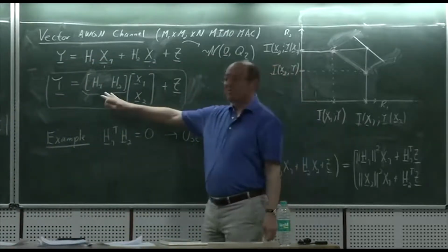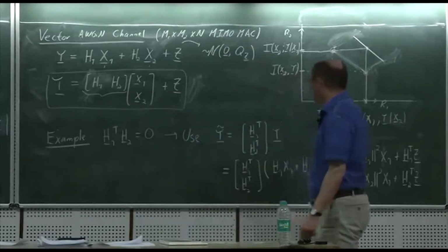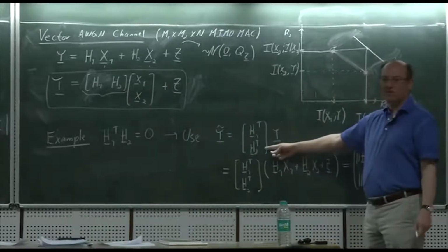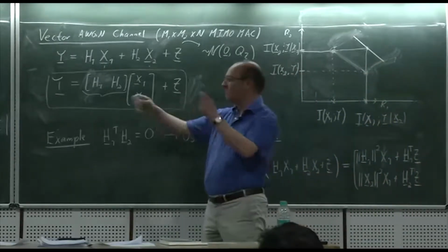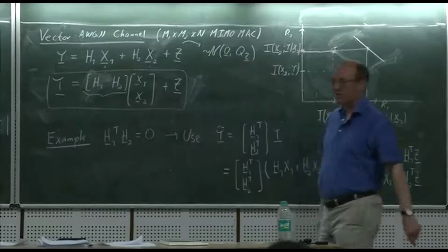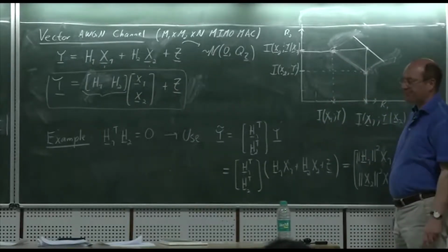We could also use an MMSE filter, and so on, if you're using linear equalization. So that's what we actually did here. We just used the inverse filter, modified by something. But anyway, we effectively used the channel inversion by choosing this approach.